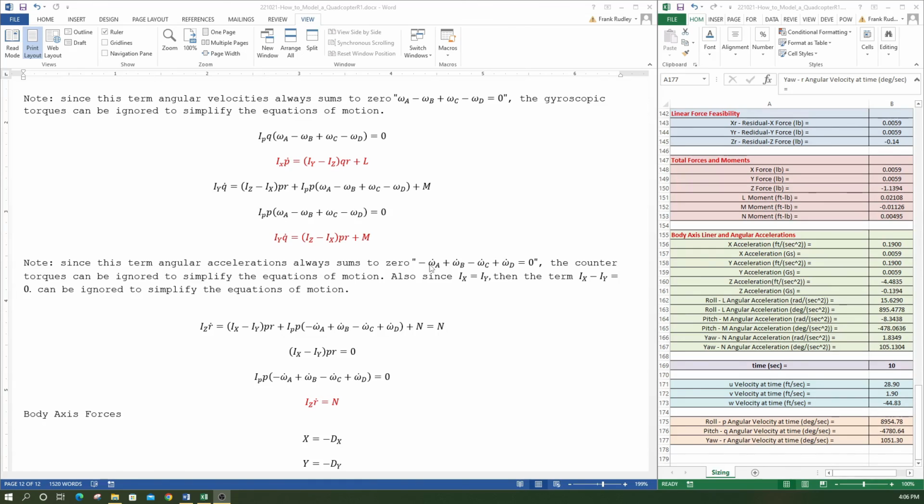A lot of people might think that the way you maneuver, especially in yaw for a quadcopter, has to do with the change in angular acceleration, but they all cancel. It's possible that they might not if you set it up that way, but normally, to prevent the aircraft from falling out of the sky, when you increase one, you want to decrease the other one. So our angular acceleration terms equal 0.